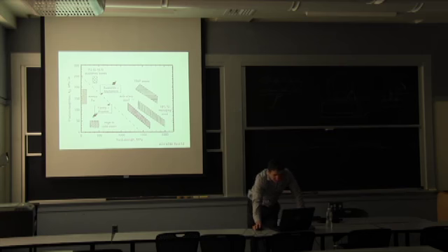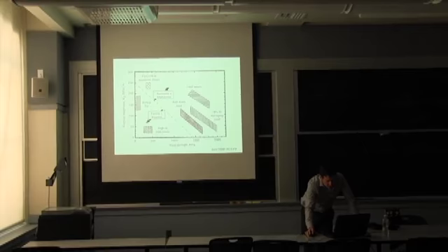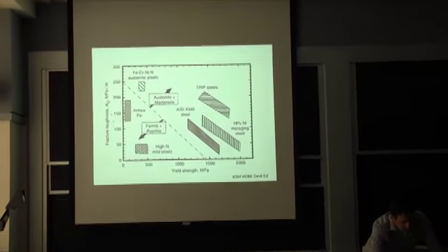What that means, the last two numbers, means 0.4% carbon. So we are pretty much in the middle of that diagram, where the optimum for cementite was at 0.8. You can get to very high strain with these alloys and still have fracture toughness.